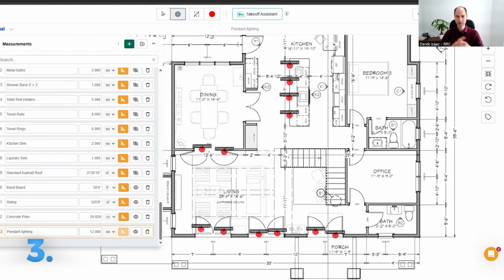Let's say through the estimating, you realize you missed something. I've had this happen where we were into a project. I was putting some bids out for tender to a drywall contractor. Their number came in quite a bit higher than what I had originally budgeted. And I found out later that I had made a mistake doing a takeoff. I had forgotten to include the ceiling for the drywall. So it does happen. And that's why this is so important, because you can really pinpoint, I made that mistake, I shouldn't do that again.